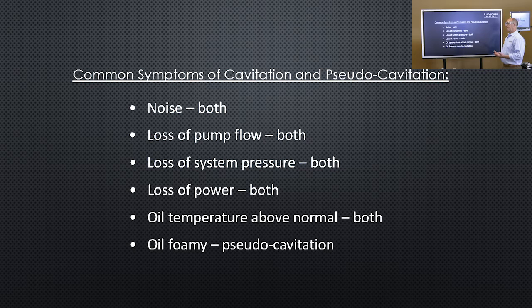Then what I'll do is I'll demonstrate cavitation. Cavitation by definition is the formation and collapse of gaseous cavities within a liquid. In other words, if hydraulic oil is made up of 10% dissolved air by volume, up to and during cavitation, the dissolved air comes out of the liquid.